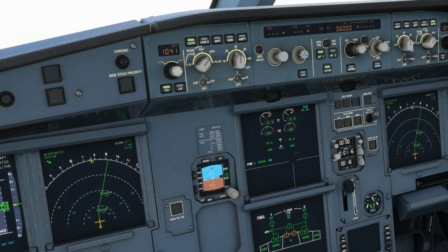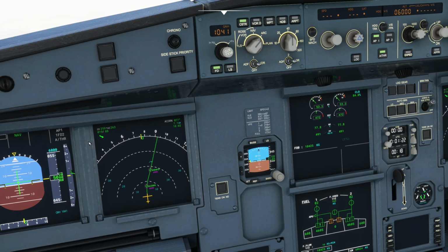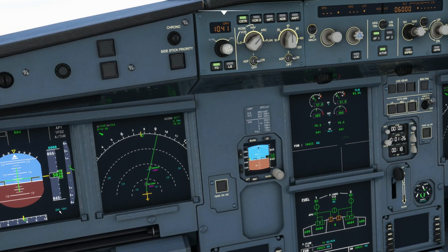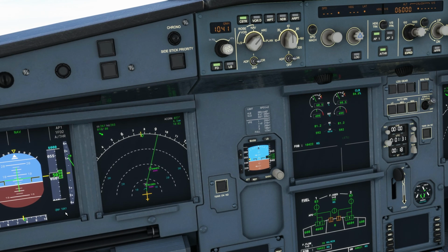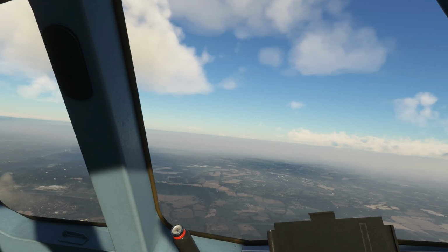It's not that busy around Gatwick at the moment, and so ATC have given me an instruction to climb to 6,000 feet a little bit earlier. So that's what I'll do. I'll now climb to 6,000 and hold that until instructed by ATC anything further, or clear of the constraints of the standard instrument departure if not using ATC.